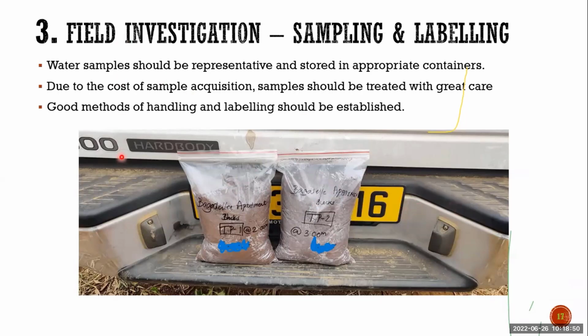We have to follow proper procedure. Even if it's water samples, they should be representative. We cannot just take some Coca-Cola bottle and fill the water in it, because it will change the properties. So we have to take a proper water container to collect the samples and give it to the lab. Then proper handling and labeling should be done.